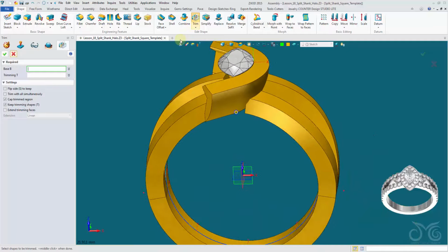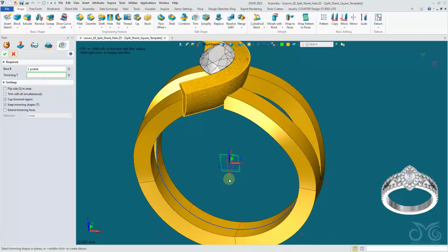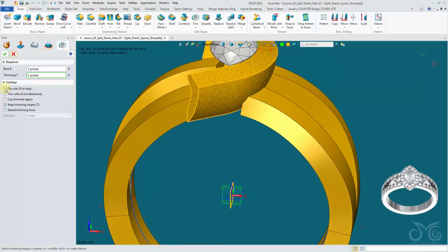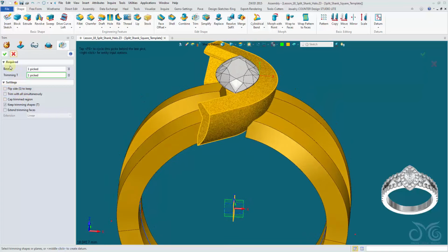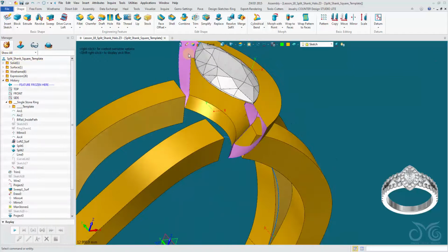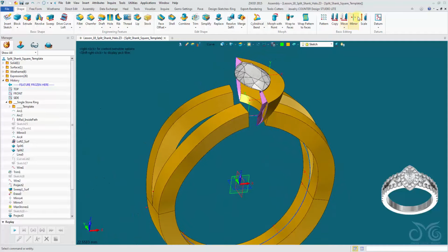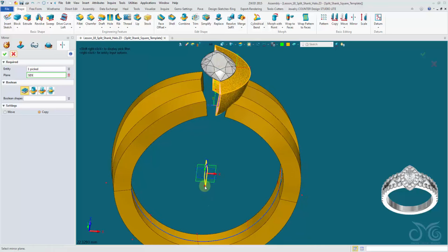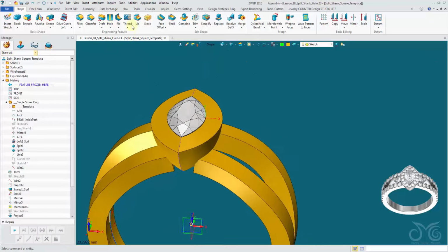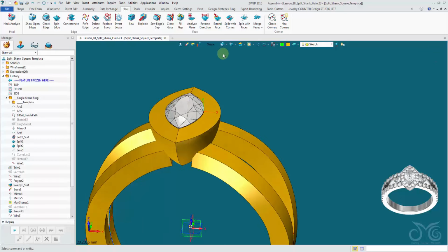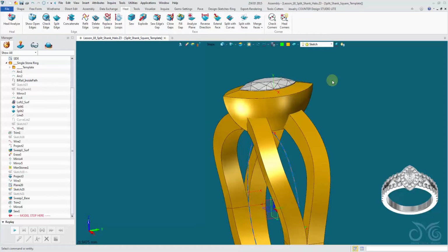Then we can trim this side, the sides datum plane. We do not want to cap the trimmed region. Let's make sure we have the right side. Yep, that's fine. Confirm. We have trimmed our halo, without the end caps. Now we can mirror this shape across that same side datum plane. And then heal it. We sew the two halves together to create one complete shape. Okay, so there is our halo.